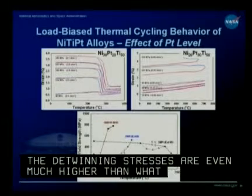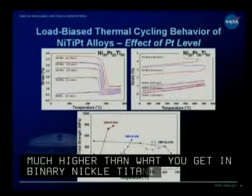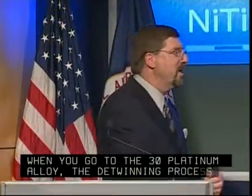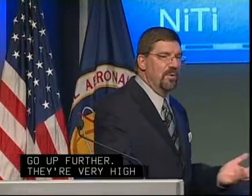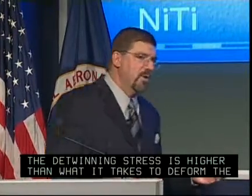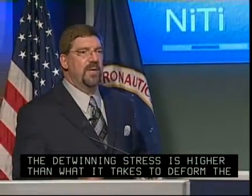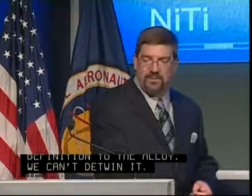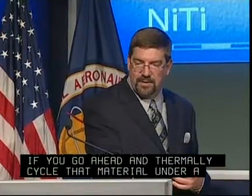But when you go to the 30 platinum alloy, the detwinning stresses go up even further. In fact, they're very high now. And the detwinning stress is now actually higher than what it takes to deform the austenite. So we're back to that original condition. We can't put any kind of recoverable deformation into the alloy. We can't detwin it, but at the same time, if you would go ahead and thermally cycle that material under load, you're going to deform it plastically because of the austenite deformation.